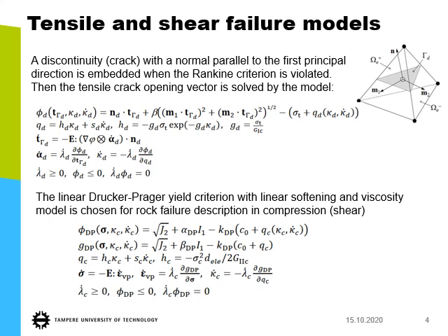Okay, we have a Drucker-Prager criterion here, and then the plastic potential. So this is non-associated plasticity. We have a cohesion, and then a softening function, a rate-dependent softening function again, similar in form to that of tension. So we have a softening modulus. This is a linear softening modulus calibrated by mode 2 shear fracture energy, and then the linear viscosity term.